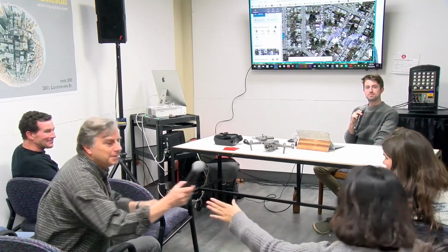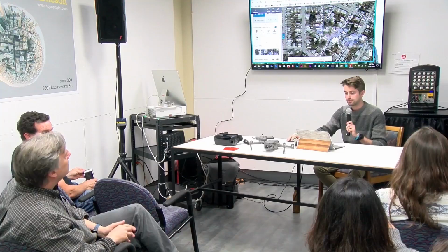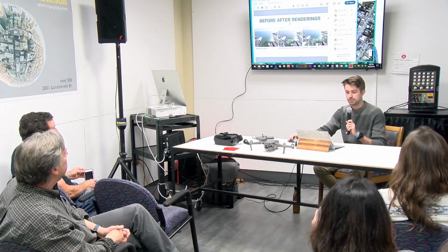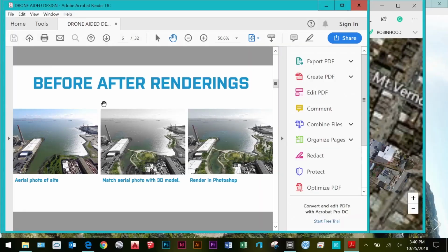Well, great. So you talk about the aerial photograph on the first, and how do you combine it with a model, after you build a model, you set the same angle and then put them together? Yeah, this one. So what you do when you take a photograph in the drone, I mentioned it's geolocated, so it will say the elevation above sea level that the drone photo is taken. So you need to mark that in the 3D model.